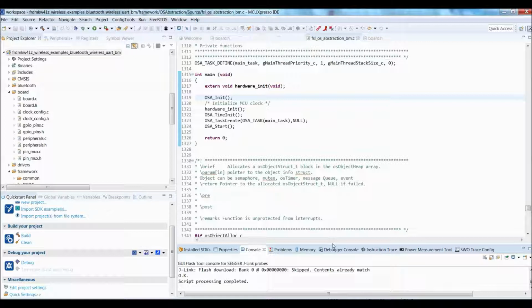pull it out of my COM port, and then if I plug it into a standard serial port, which you can't see, it's off screen, I'm not going to bother showing that. When I do press it, the LEDs will run the same way. First no LEDs are on, then it starts to come up with both LEDs flashing. I hit the button SW4 and it does go into advertising mode and trying to bond and pair. So I will now unplug that one.